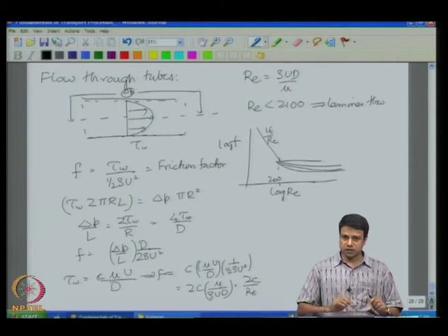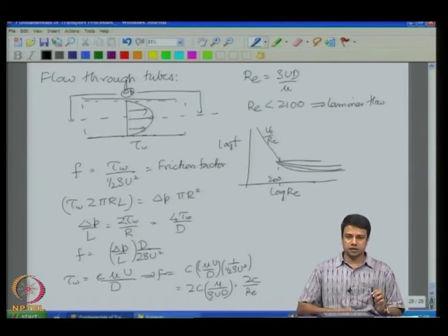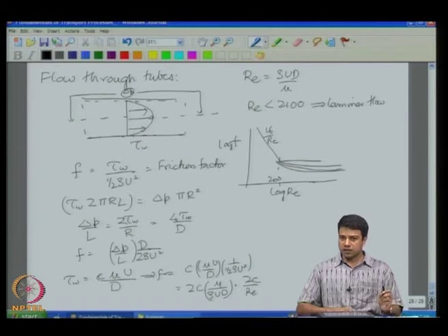Those dimensionless groups have interpretations. They are mostly either the ratio of convection and diffusion, Reynolds number, Rayleigh number. They are the ratio of two different diffusivities. Okay, for example, the Schmidt number is the ratio of momentum diffusion and mass diffusion. The Prandtl number is the ratio of momentum diffusion and thermal diffusion. Okay. In the case of natural convection, you have dimensionless groups that are a ratio of, once again, convection and diffusion, except that convection is caused due to buoyancy forces. Okay.